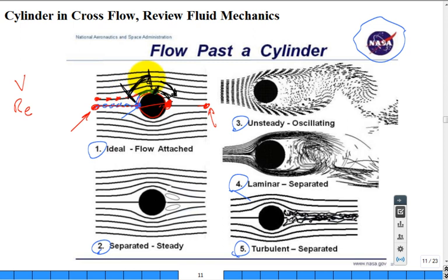This flow right here was speeding up, moving into a region of low pressure. That makes sense. Speeding up, moving into a region of low pressure, they call it a favorable pressure gradient. But the other one, slowing down and moving into a region of high pressure, fluid is like a wiggly worm. It wants to escape. It doesn't want to do that. That's an unfavorable pressure gradient.